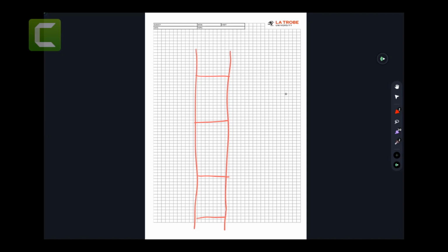Sockets basically, if I look at the side of the slab, this is the slab and that's the soil under. Usually they make a socket here every 2 meters or every 1.5 meters, because if they keep it too long without a socket, then the whole piece, let's say a 10 meter long slab, and usually these are about 1.5 meters wide, depends on the council.